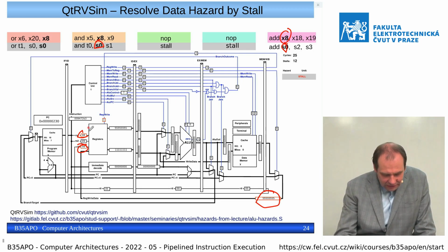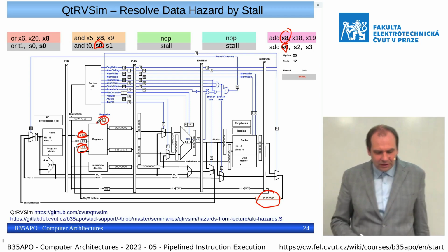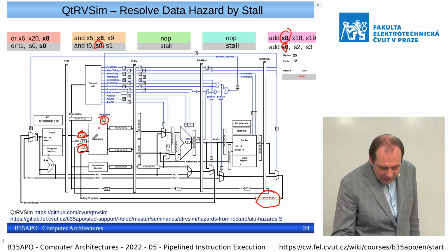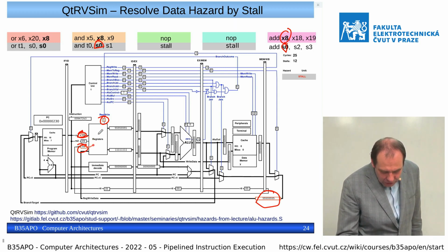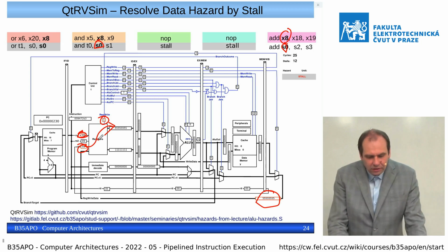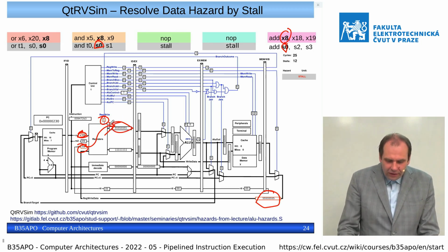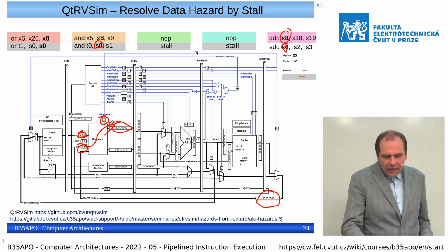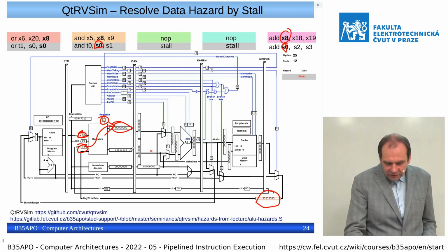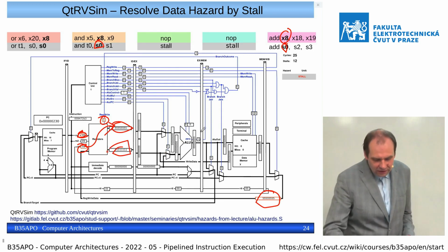So in this case, we know that there is a request to read physical register 8, and a write to register 8, which is shown here. So basically in this case, we can propagate the information from the written register to the read register, and we get the correct value 555. And in the next clock cycle, this instruction advances to execute and adds this with 111, and we get the correct result 666.